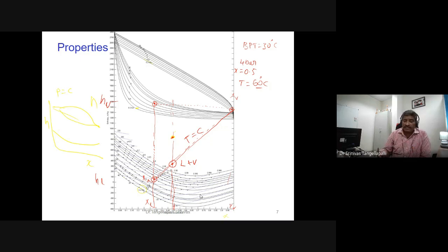We have 5 minutes. I will give you a small task. Could you combine the mass balance and the energy balance equation here? M is equal to ML plus MV. And H is equal to HL plus, the dryness fraction, times HV minus HL, where the dryness fraction is equal to MV by ML plus MV.